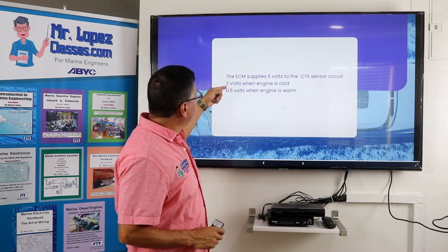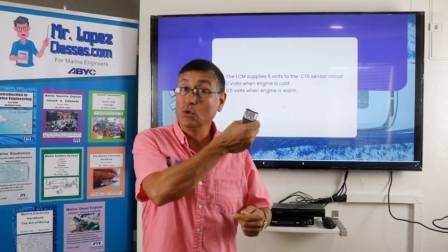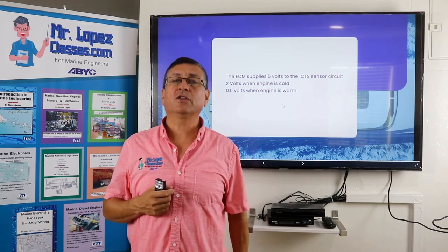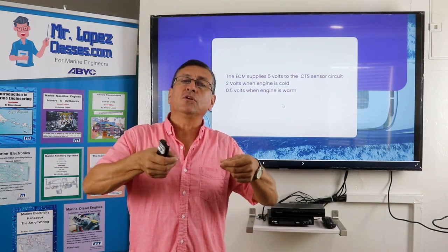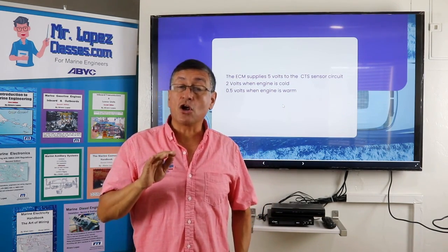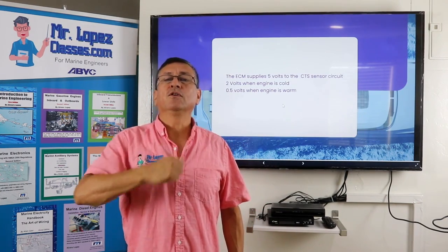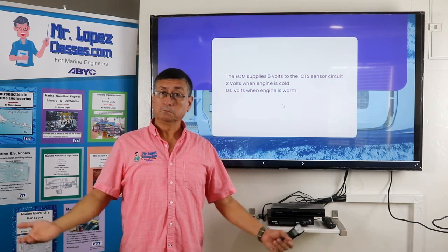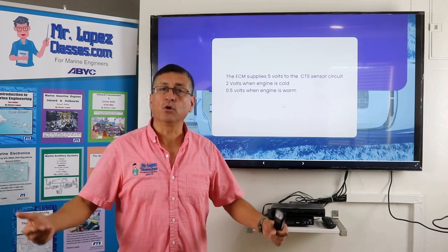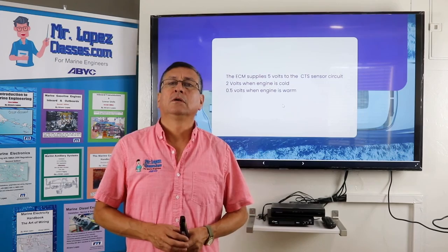How can I verify those voltages? Oh yeah, with the tool that I explained at the beginning with Mr. Rodriguez. You disconnect, you connect the tool in series, and with the engine running at operational temperature, you verify those voltages. Complicated? No, it's simple. That's the procedure.